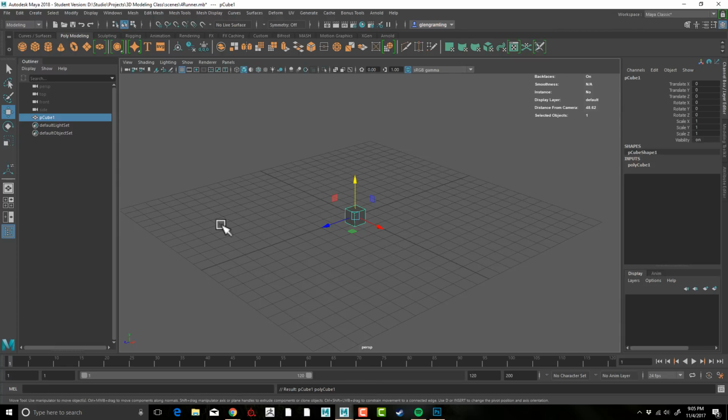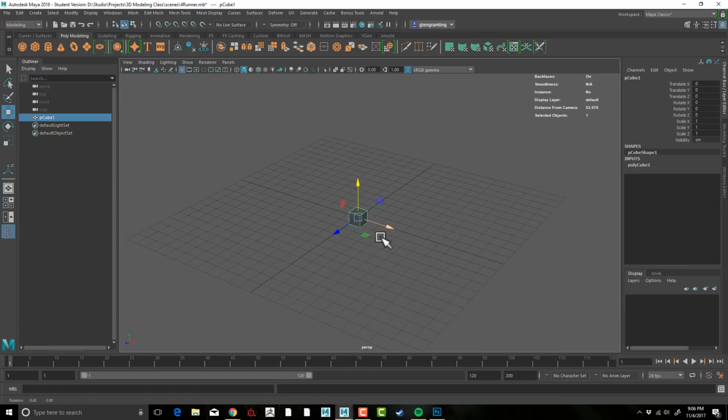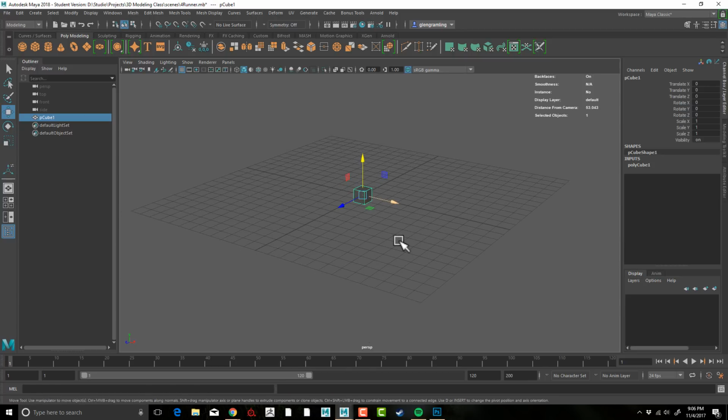They'll model a house based off the size of the grid, and then try to light it or add dynamics like cloth. It just doesn't work, because you're applying dynamics that are based off real world physics to a 5-inch house or a 5-inch car, because that's about the size of our grid here.